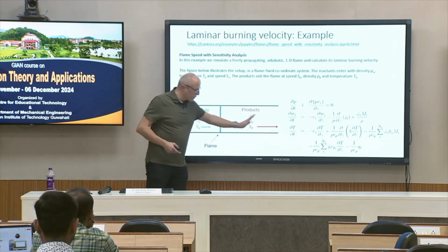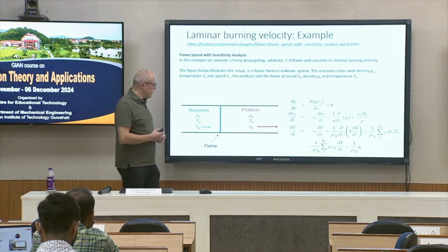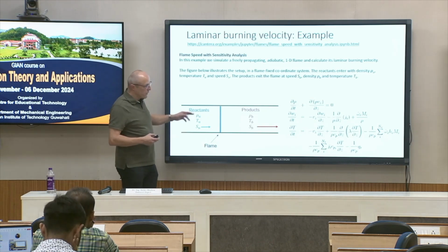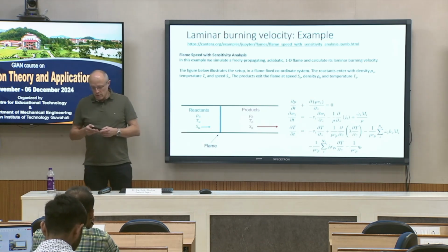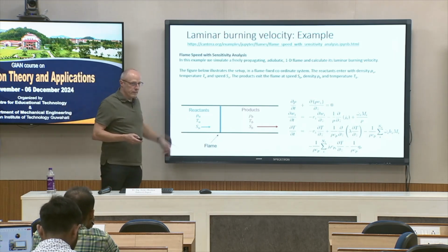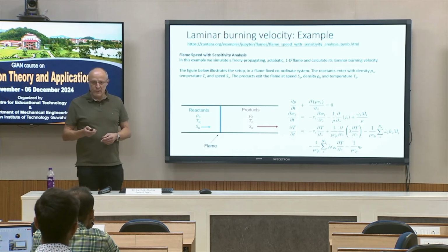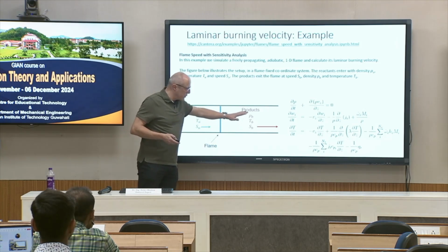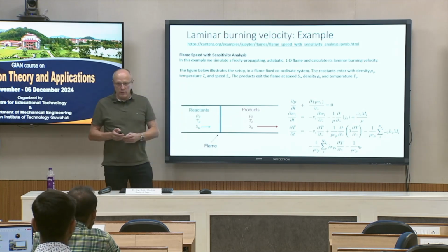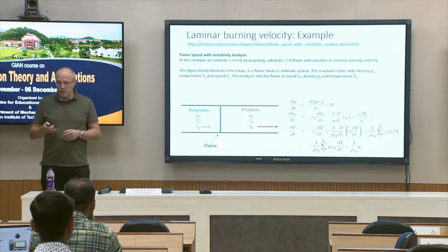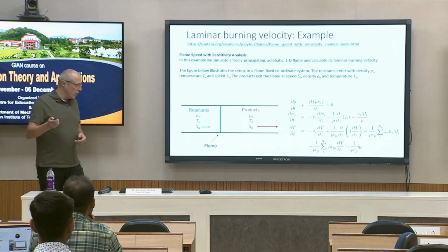Pressure is constant all over the regime, so temperature changes, density changes, of course, and velocity changes, because finally velocity times density is constant for our system. So if we decrease the density due to the combustion process, we then have to increase the burning velocity, the flow velocity.